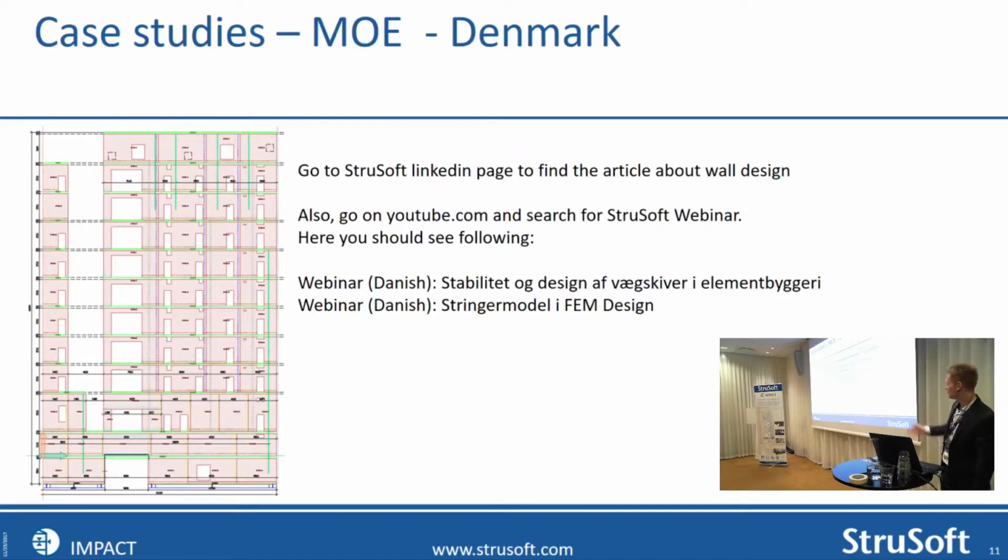So what we do now, when they removed all the walls in the length direction of the building, we need to activate the facades, and they often look like this. It's chaotic. So this FEM design is widely used for this, to design these openings, to make sure that your openings, your edges, your corners can take this force that it needs to take for calculating stability like this.